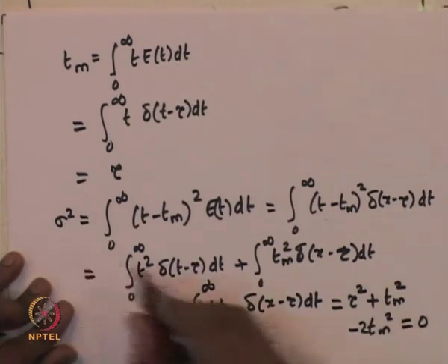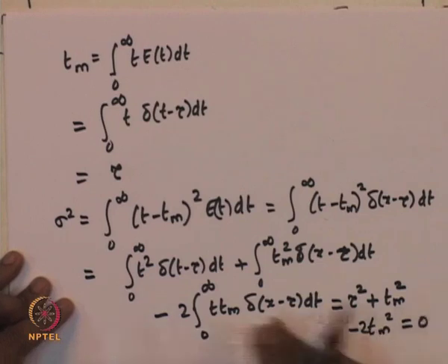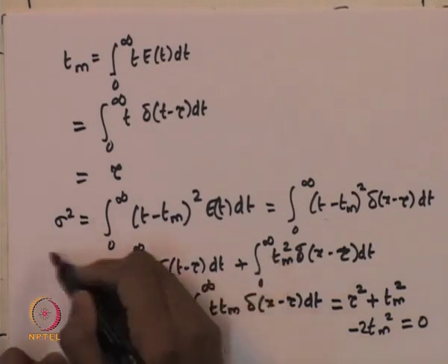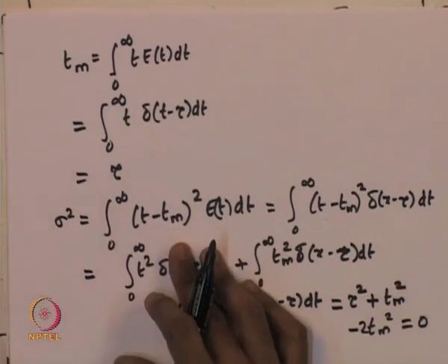So, therefore, the variance is actually equal to 0, and that reflects the property of the RTD function that we intuitively guessed. That is, there has to be a spike at exactly t equal to tau with an area under the curve equal to 1, and the height of the spike equal to infinity, which means that the variance should be equal to 0 for the distribution.